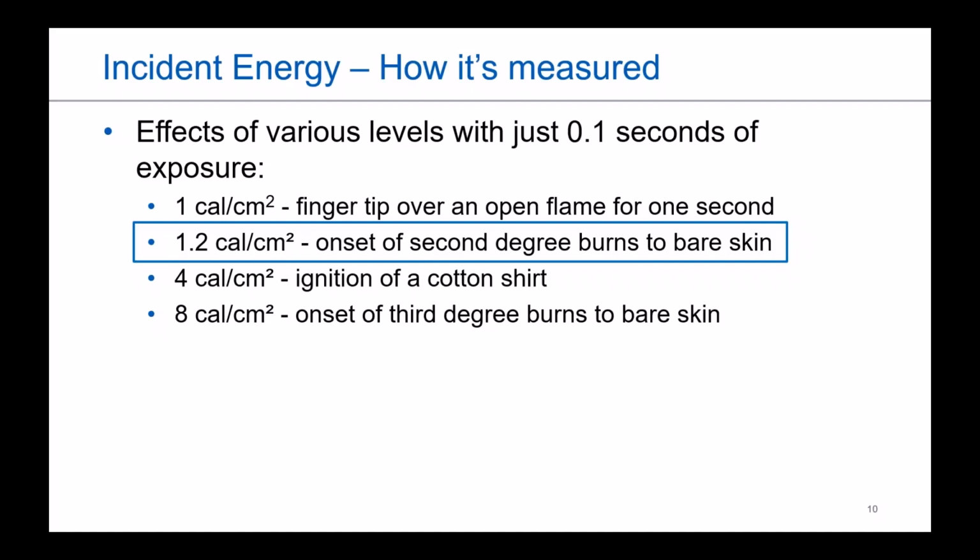So that has become a threshold throughout the electrical industry of where we want to try to get things, so that if someone were exposed, say they didn't have the proper PPE on, as long as they're getting hit with that level, it's still something they can walk away from. Is it going to be pleasant? Are they still going to be hurt? Yes. But the idea is that they can still walk away from it. They're not going to have to be carted out. They're not going to potentially have skin grafts like you would at a third-degree burn level.